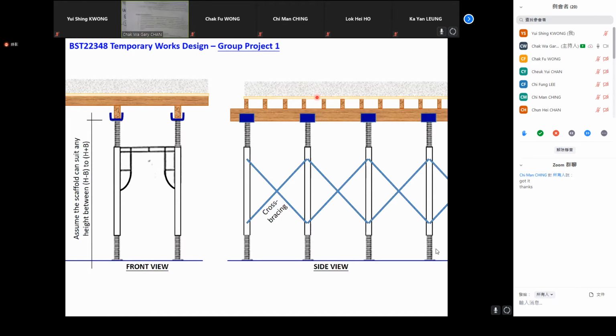So when you do the checking, you have to do it step by step. You can refer to design requirements. The first one is the allowable deflection for plywood and timber is span over 270. That is the requirement for checking the deflection for the plywood, joist, or the bearer. The allowable deflection should be span over 270. Okay, and the second one is check the plywood.